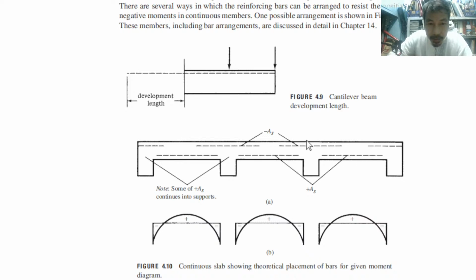But at the support itself, the tension side is on top. Take note, if we are talking at the support, the tension side is on top. If we are talking in the middle of the span, the tension is at the bottom.